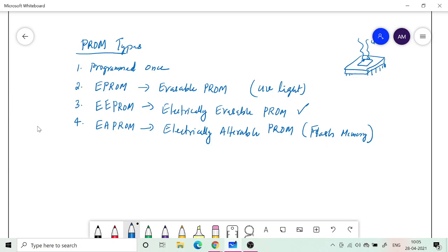Okay, so PROM means, you know, the architecture I have already told you. It has first a fixed AND array. It is generating all the minterms. Basically it is a decoder, followed by an OR array, and every time you store, basically you are changing the connections. The details depend upon how it is implemented. It would require a special type of transistor, a floating gate MOS transistor.